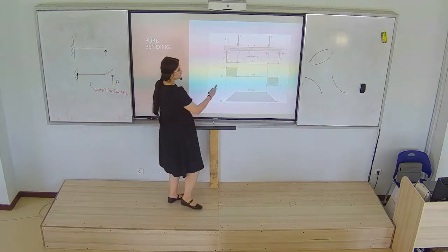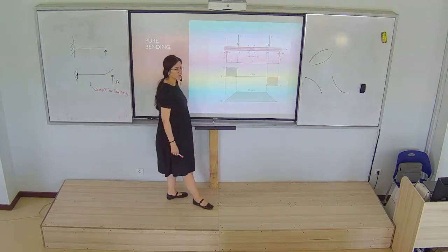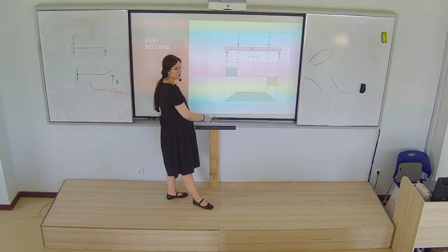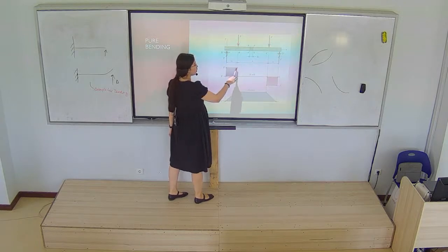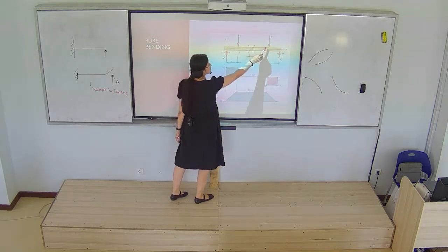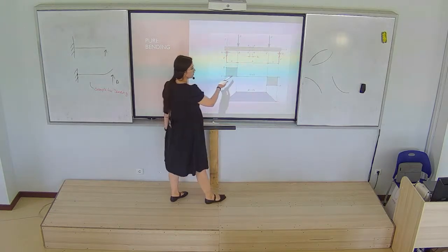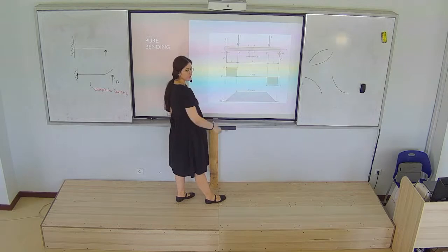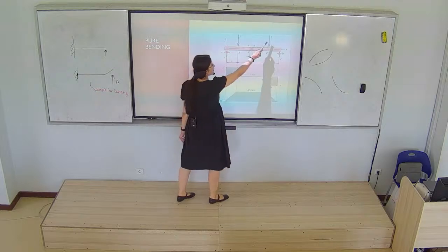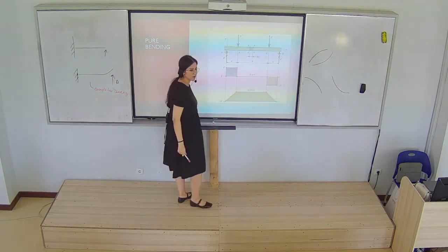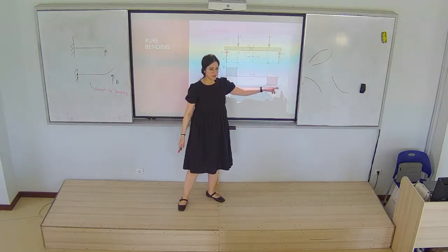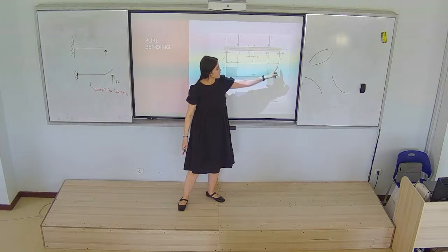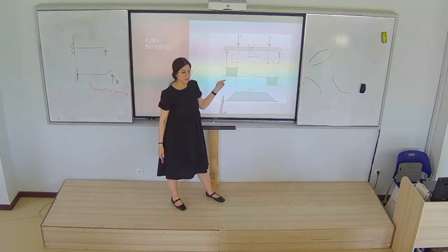So, in this part, our diagram for shear. Is it understandable for shear? Because P is going up. Yes, it's going up. Until here, we don't have any force. It will go down. And until here, we don't have any force. It means that it will change just through the line, so it's equal to 0 here. After that, we have again P, and it's going down to minus P. As this is the minus side, our direction will be downward. This one is upward. It means that our diagram is correct.